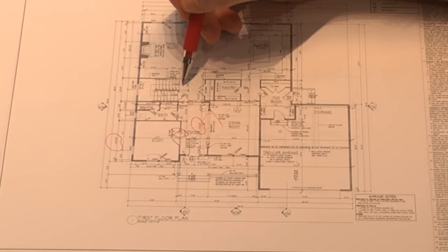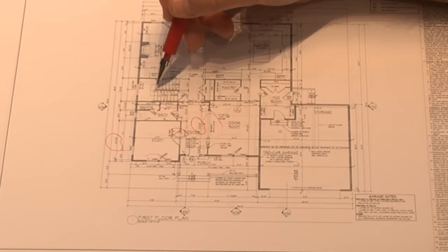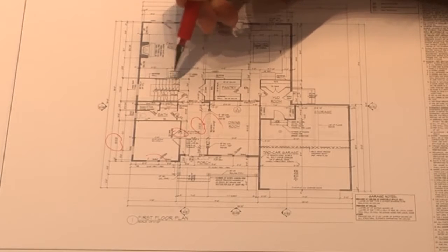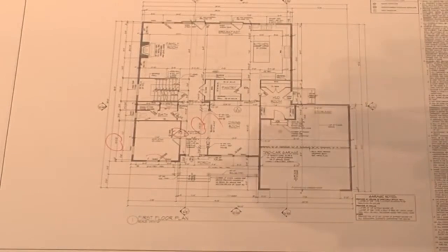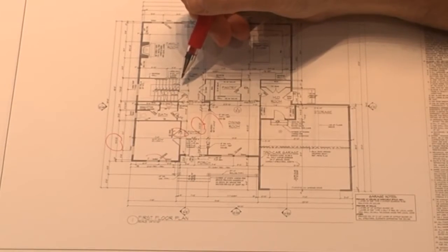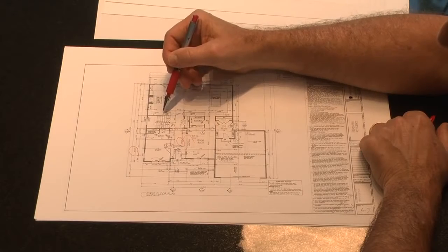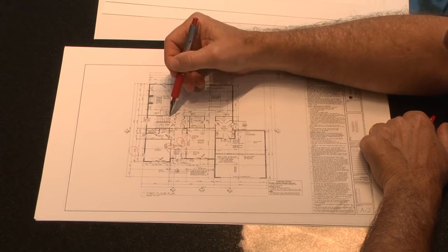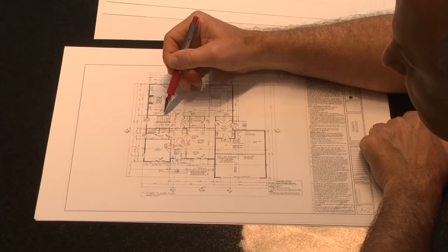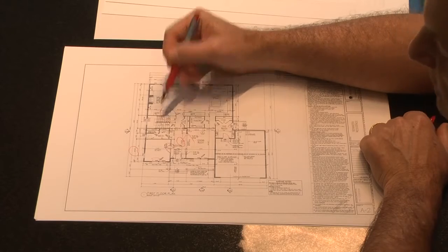And that means when you're standing on the floor, you're at the first kind of step level, so to speak. So 2 just means the second tread, third tread, fourth tread, so on and so forth. So to go upstairs, you would have to travel 16 risers or 16 vertical increments. That would equate to 15 actual treads, physical treads. In this plan, it's also showing an opened rail. It starts at this first tread and goes up until the 1, 2, 3 to the fourth tread.